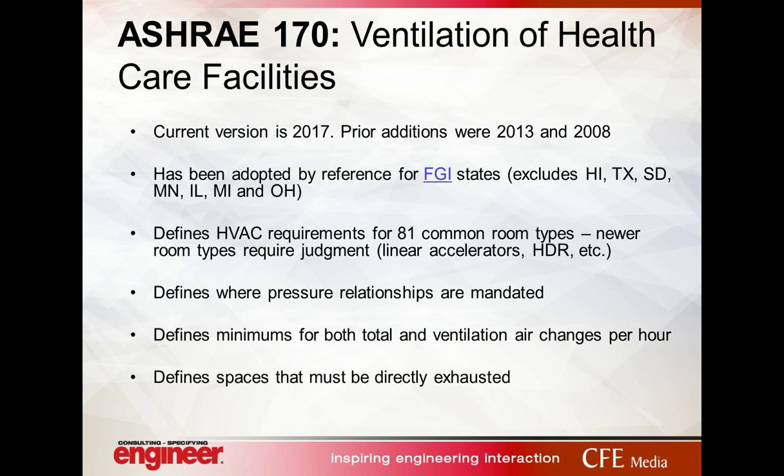So ASHRAE 170 might be the most important healthcare standard that you need to be aware of. It'll govern almost all aspects of the ventilation of various room types that you'll see in a hospital. It'll govern things like the pressure relationships you have to maintain between rooms, the minimums for the total air changes and the outside air changes. It defines spaces that you have to exhaust 100% of the time.